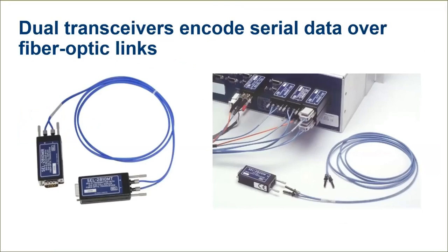And of course, fiber optic transceivers encode and decode copper, or EIA-232, signals over a fiber optic cable. Unfortunately, there are few industry standards for encoding the serial fiber optic connectors, so third-party devices often don't communicate end-to-end on the same fiber optic side of the communication network. The following factors must be considered when selecting fiber optic transceivers for communication links, such as how much available